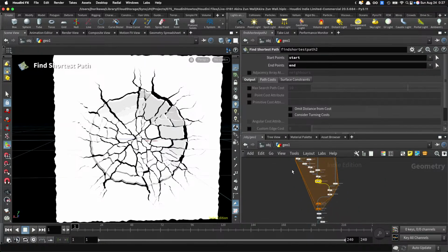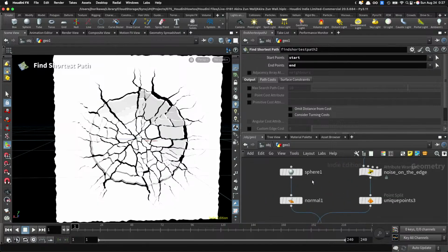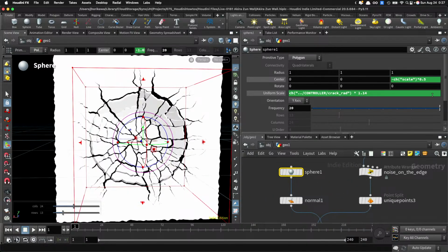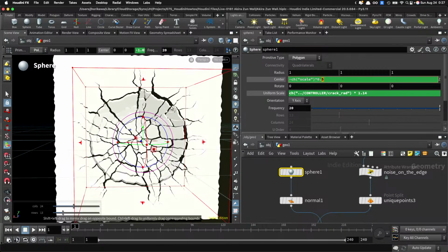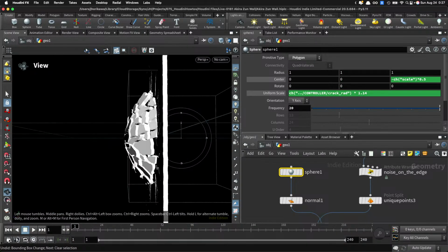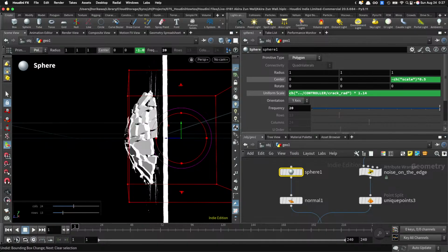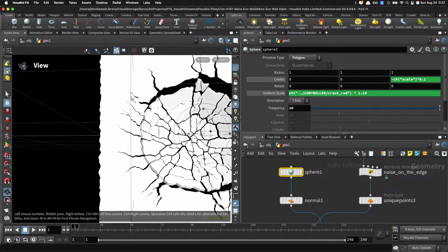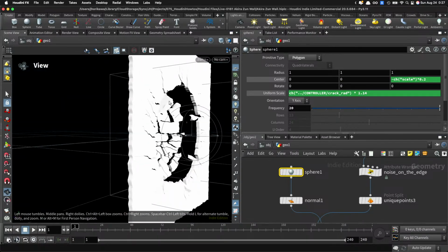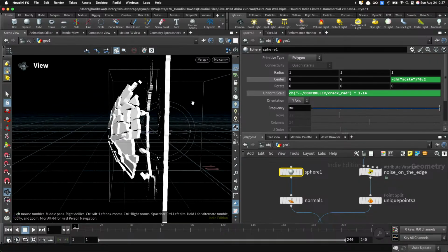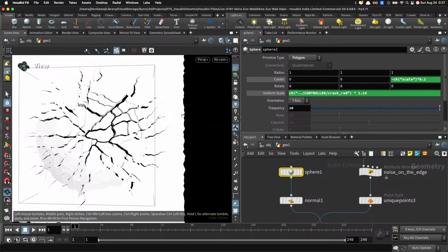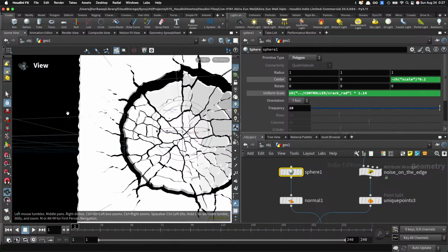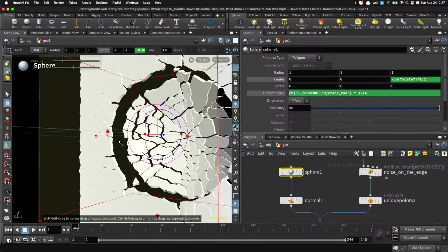And oh, one thing, you might also want to be able to control this scale as well, so that you can control how much curvature this hole has. So if you make it 0.2, you have more depth, and you start to see edges not being followed because these parts are not being intersected.